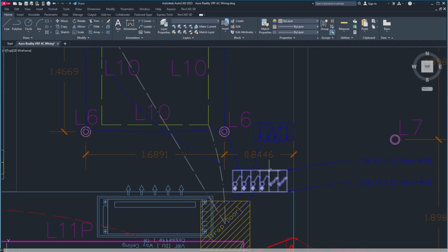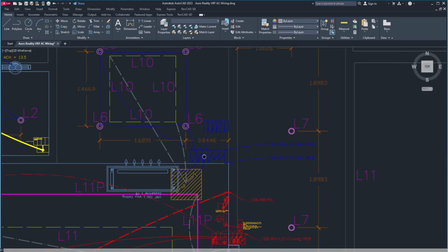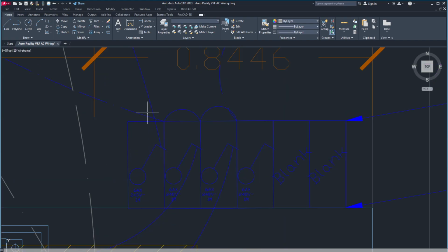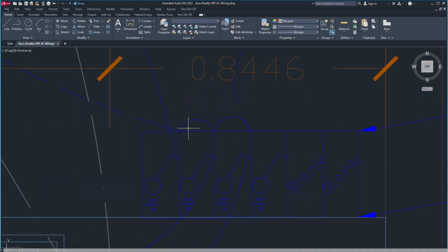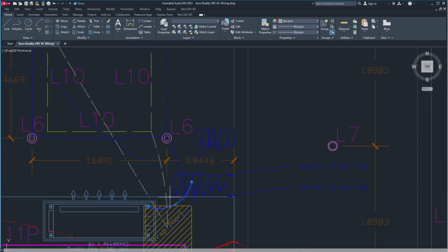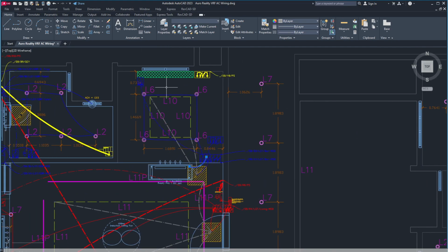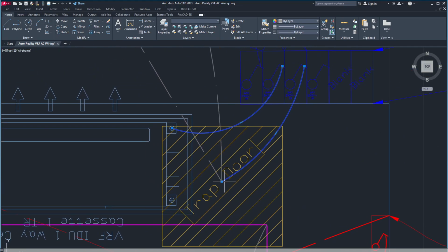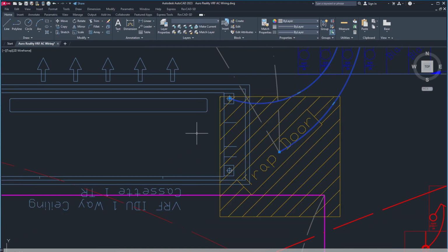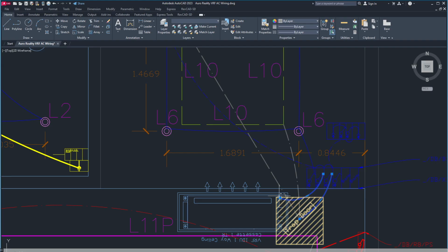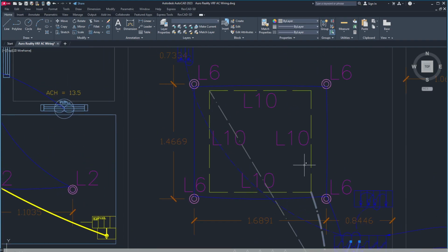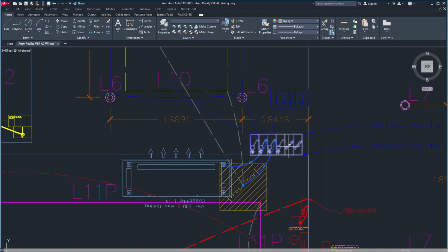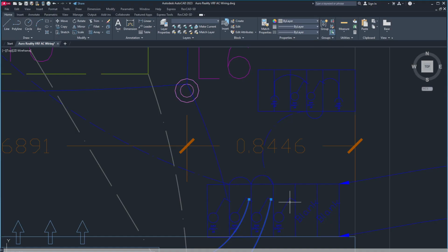So basically, this is the main switchboard which is controlling the bar area. This is for the downlights as usual. Then this is for the AC blowing the air. The AC is blowing the air like that. And this one we have drawn to the trapdoor. We have placed the driver here. See, the trapdoor is also serving this AC. So this is proper engineering. From here we are drawing the DC lines to these coves. And one more switch I have given as a spare, and two blanks.